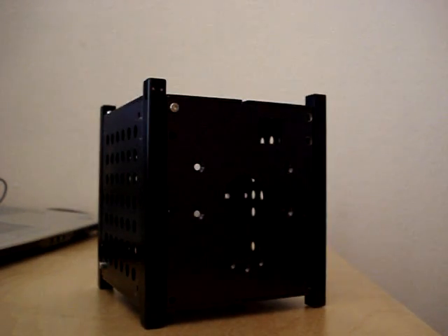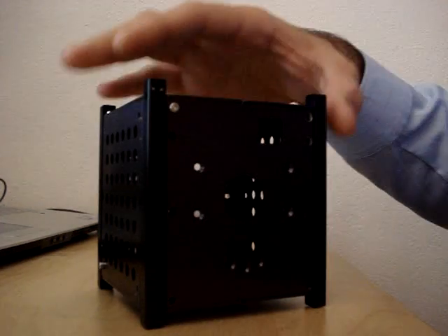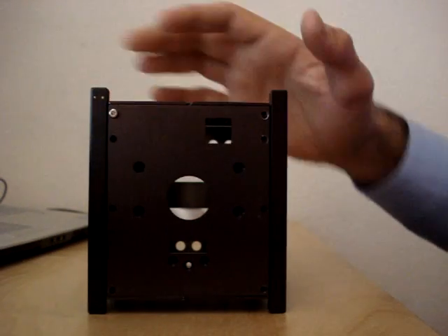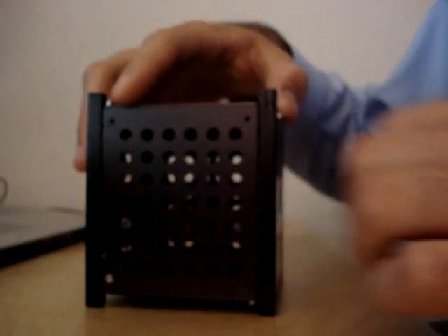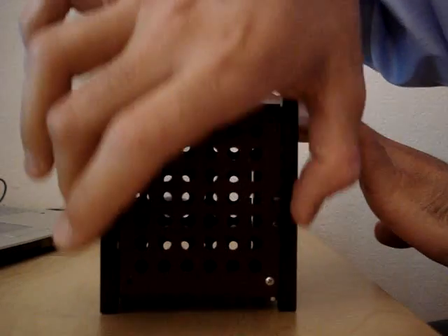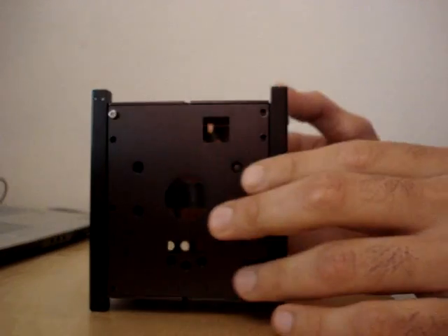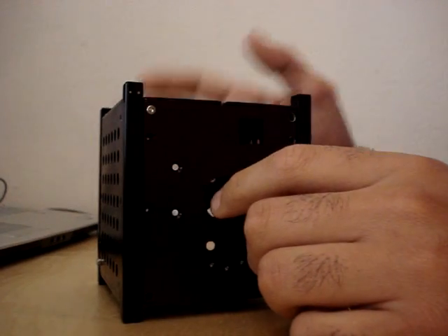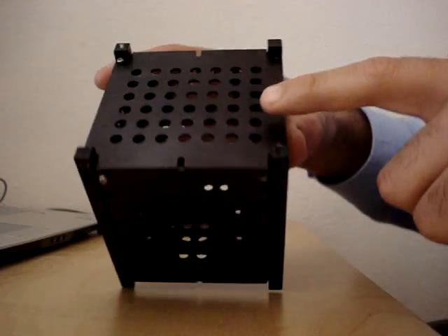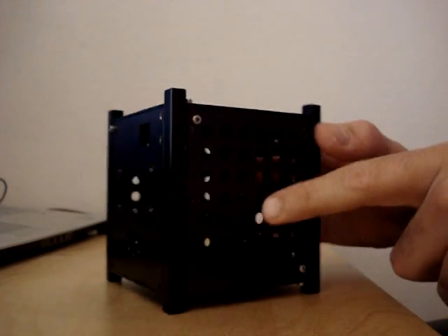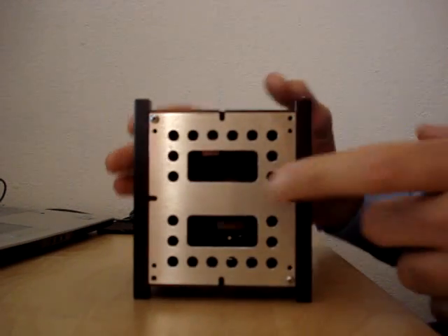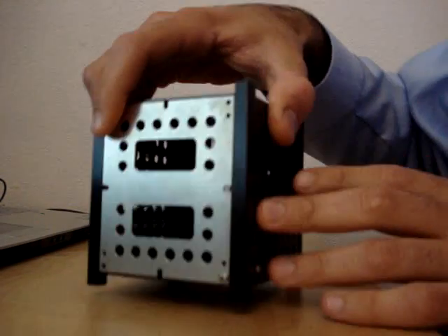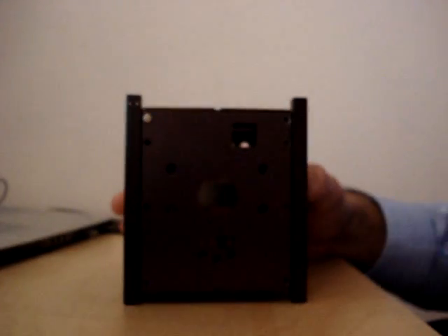It was basically my job to build a structure that could support the weight of everything inside the satellite and survive launch forces. I started by designing primary and secondary structures. The primary structures are the two frames, the left frame and the right frame. And also the primary structures include the 6 panels: the top panel, the right panel, left panel, back panel, bottom panel, and lastly and most important, the front axis panel.